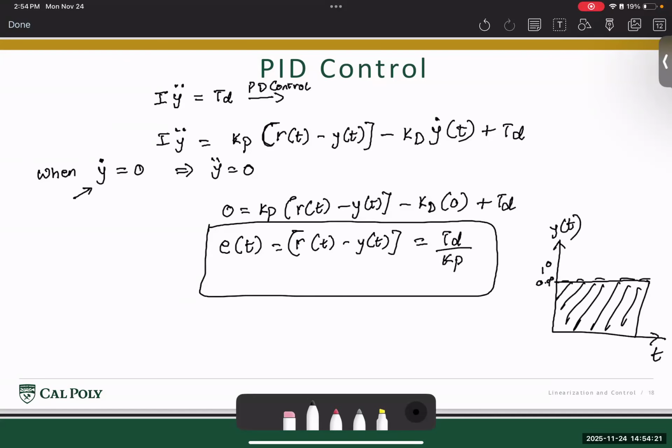So what the PID controller does is that it looks at the total area under the curve, which is the summation of all the errors. Here area is given by the integral from 0 to t of E of t dt, and the PID controller adds an integral term which we said is given by Ki.